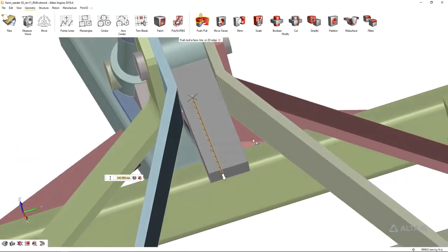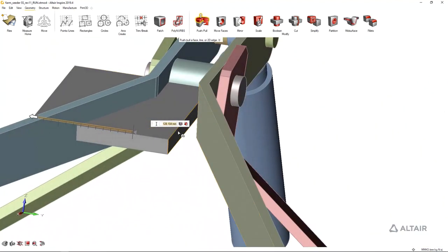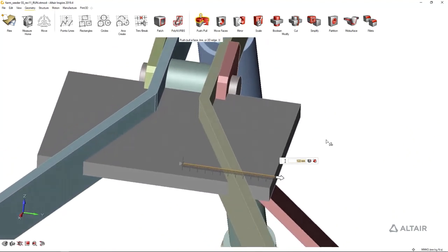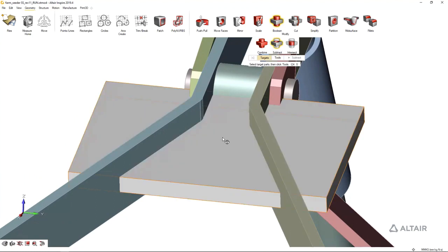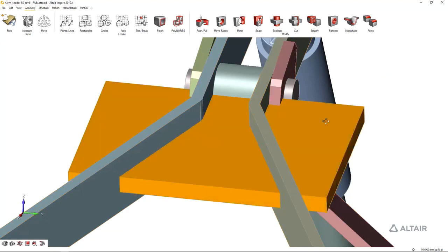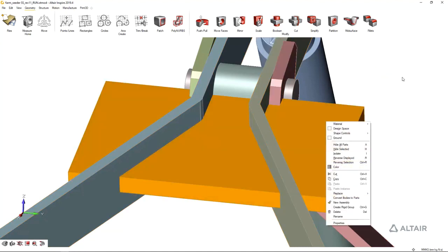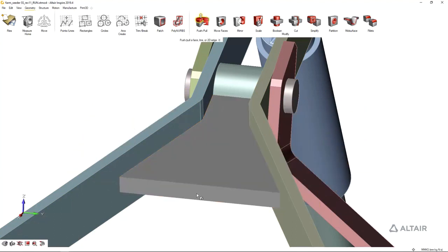me drop the stresses. So as you can see here in the video, I'm picking a face, just dragging it in any direction. You can change the length, the width, also the thickness, and then I'm trying to trim off the excess portion of this particular reinforcement plate. So I'm going to Boolean operate it, remove those two volumes, maybe change the thickness also a little bit. So I'm going to drop the thickness by about 20 mils here.